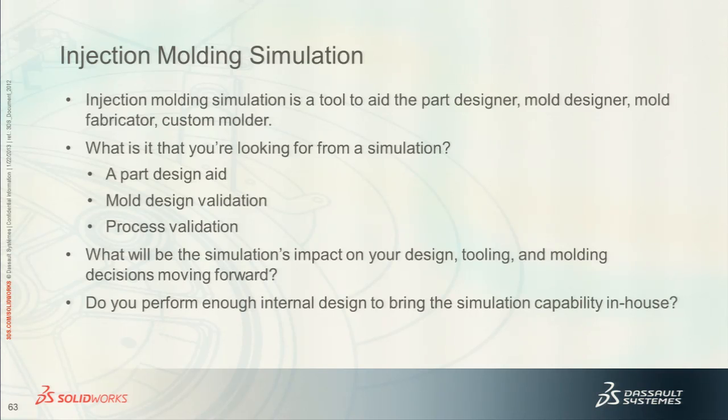I have gone down to 60 thousandths. Thinner than that point, I was told that you do not get an adequate microcellular structure. There's just not enough cross-section there. And now injection molding simulation, that's probably about 40% of my business these days.